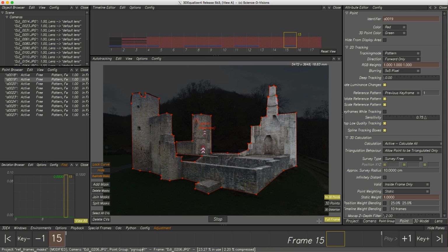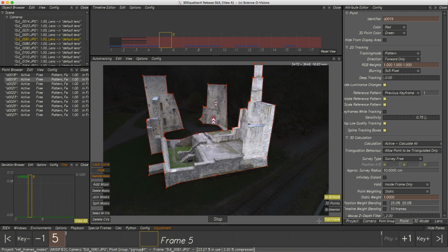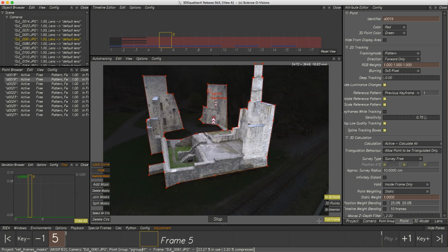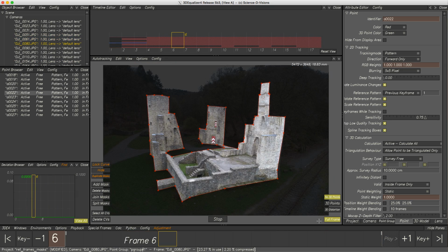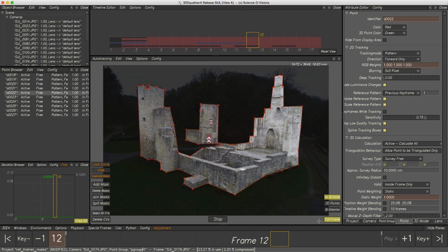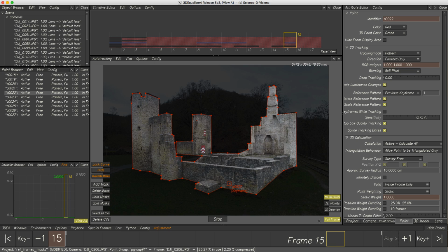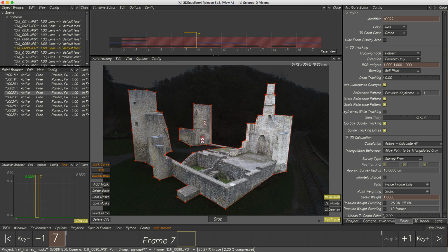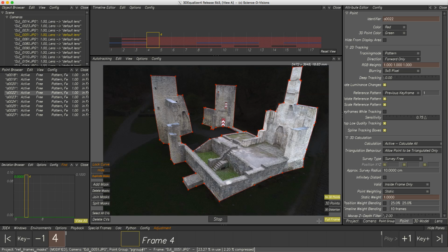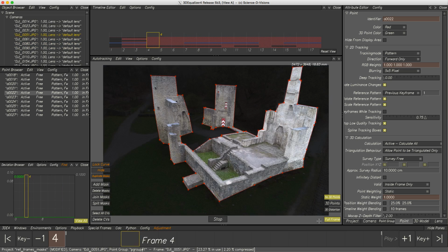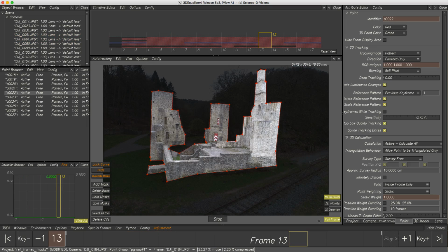In this pass, the auto tracker uses the same technique we applied previously to fill the gaps. Already tracked frames will be used as a new reference to try tracking the remaining untracked frames. How many times this second pass will be applied was set with parameter max passes per point. In our case, 5 times per point. After that, again pass 1 starts with finding new features in a different frame. Time for a nice coffee.